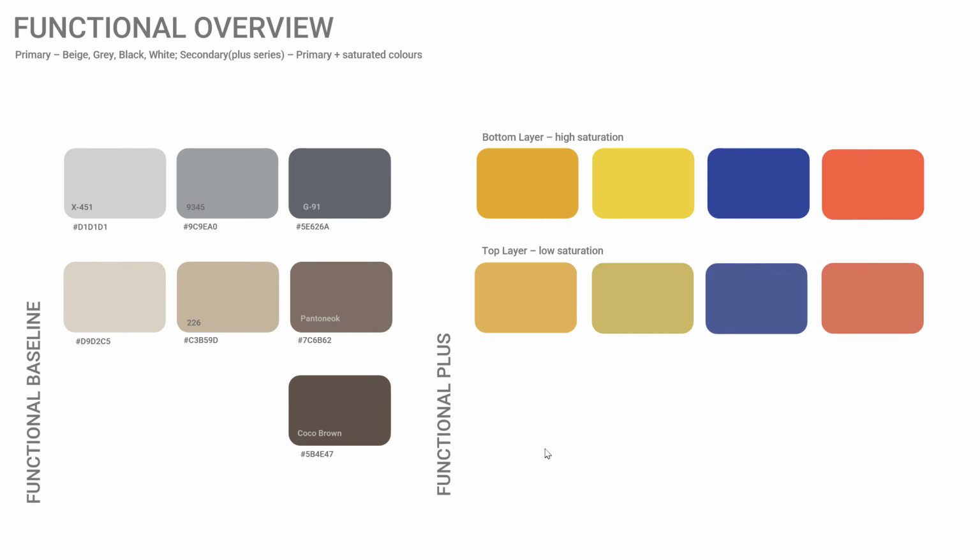So we have two families, to be very brief, defined in denier: 6 denier and 12 denier. 12 will be mostly for carpet application, heavy usage. And 6 will be used in things like headliner, package tray, or load floor.